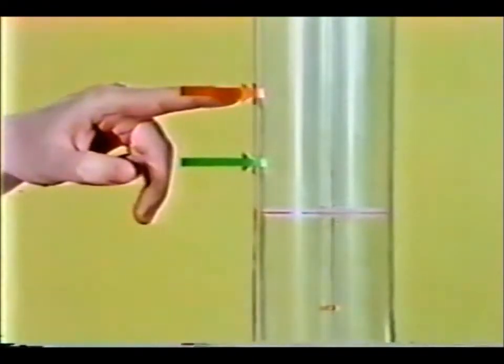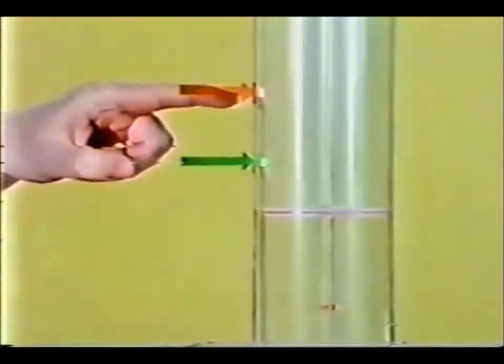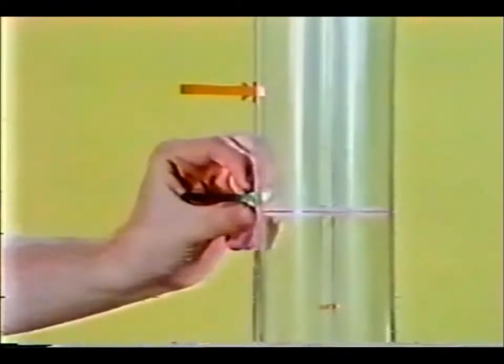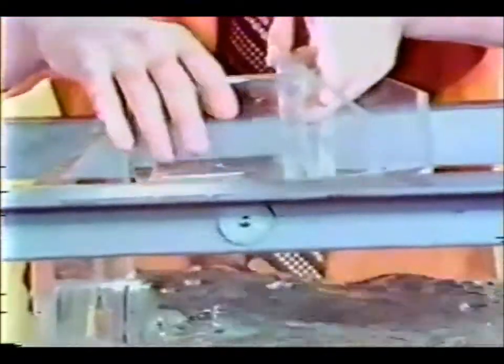The headwater pool elevation for the thin wall projecting is here, and for the bell mouth entrance is here. The difference is about 1 pipe diameter. Placing the bell mouth entrance in a head wall will not improve performance. The headwater elevation is about the same as for the bell mouth projecting entrance.